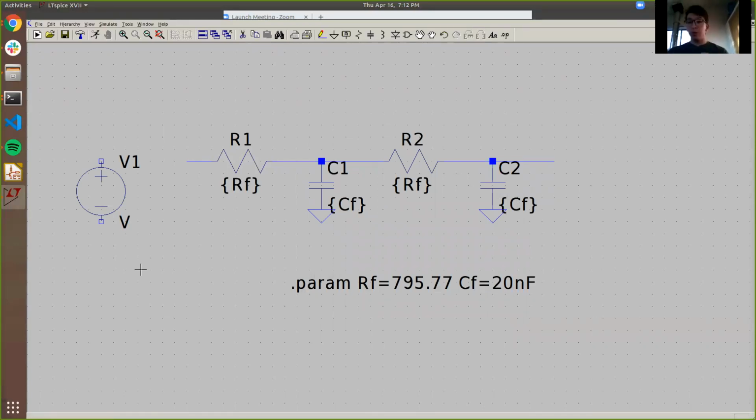So what we're going to do is make a Bode plot of this. If y'all recall from ISIM, a Bode plot is you're looking at the frequency response of your circuit. What that means is you're trying to see what the output is versus the input of a specific circuit. In this case, we're doing a filter. So it's going to be sending an AC wave of varying levels of frequency to the input of your circuit, and then you measure the output and compare them together.